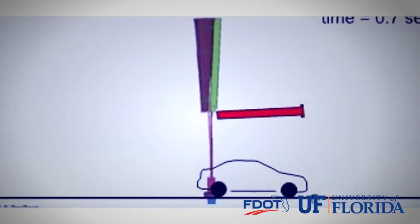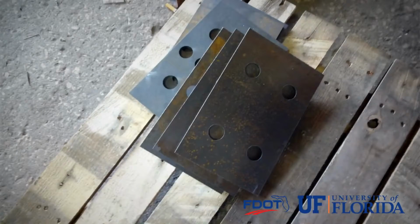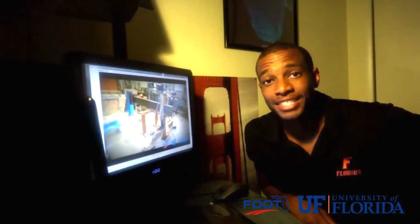At the final rotated position, the hinge plate holds the detached post leg in place and keeps the post leg from rotating back into the impact zone. The fuse plate and hinge plate have been designed with the capacity to resist 150 mph wind loading. I hope you all are still with me because it's about to get really good.